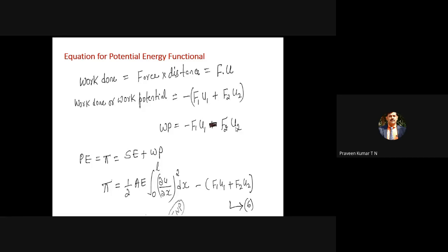In simple terms, the energy approach means the system is in equilibrium only when the rate of change of energy is zero. Energy itself cannot be zero, because thermal energy becomes zero only at 0 Kelvin. But in finite element analysis, you say that only when the rate of change of energy is zero, or the variation of the energy is zero, is the system in the equilibrium condition. That's why you studied variational calculus.